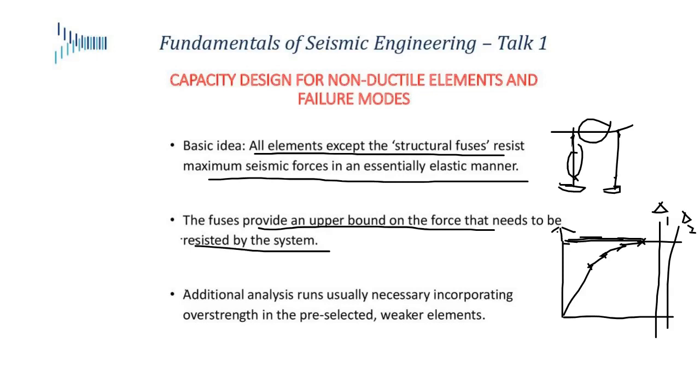So imagine if your column is 1 meter in diameter and it has a certain bending moment in it. Now my earthquake comes along and it increases that bending moment from gravity, and it pushes it all the way to its limit. So now it's formed a hinge. How much force do you think is going to get into the foundation and the cap beam after all 4 hinges have formed? This much.